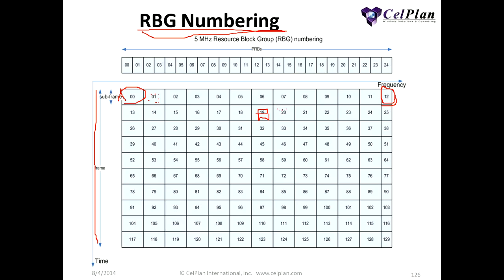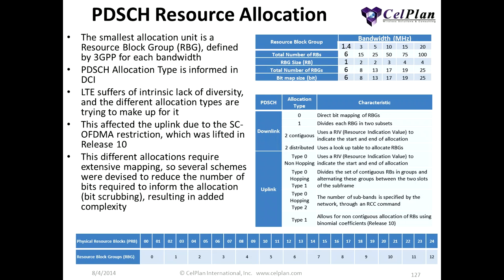Then you have the other reference signals. There are about 8 types of reference signals. And this does not include the first 1, 2, or 3 symbols that are the control area. This only includes the remaining symbols. And you will see later, in release 12, the issue in the control area is so critical that they are now allowing use of part of the data area to send control information mapping.